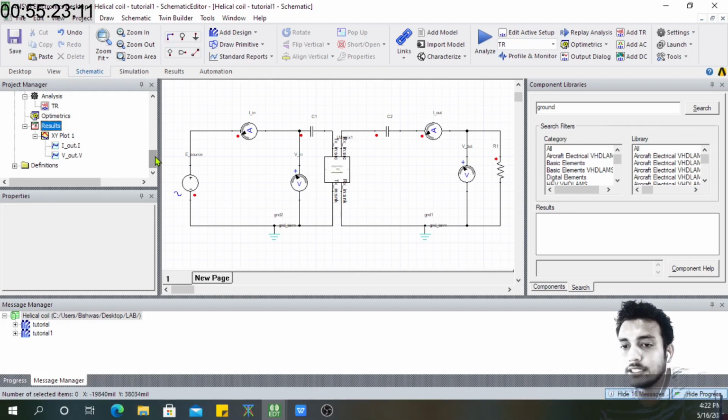So what you can try is, at least if you're trying a practical circuit, where the size of the circuit is very practical, you are using a 200 diameter of coil and all these things, then please make sure that when you do the frequency sweep in the eddy current loss solution, while calculating the losses, you use very few frequency points, otherwise it will take a lot of time.